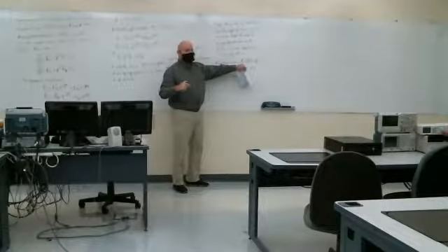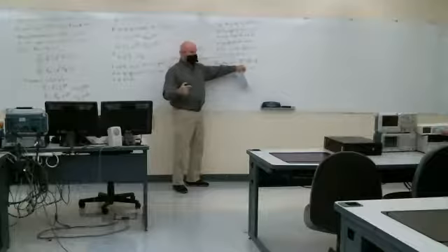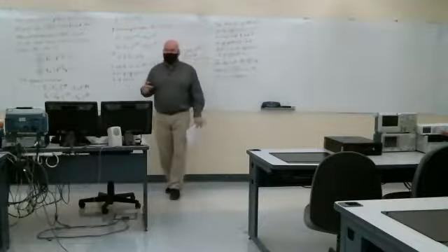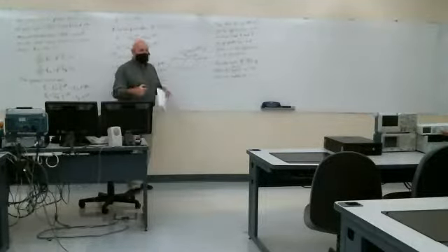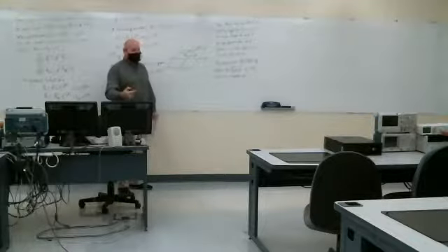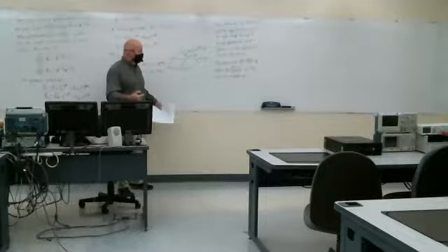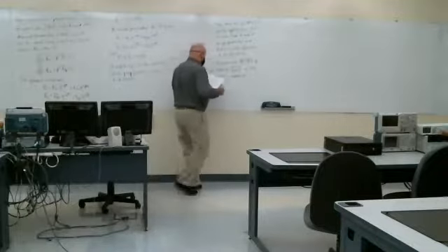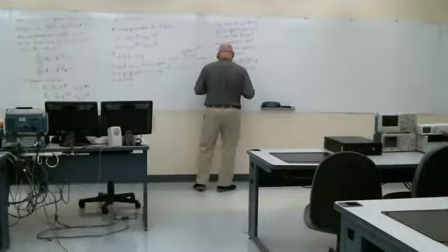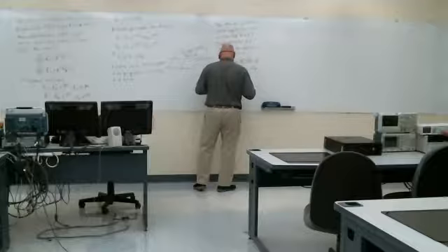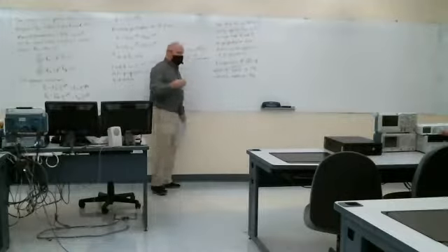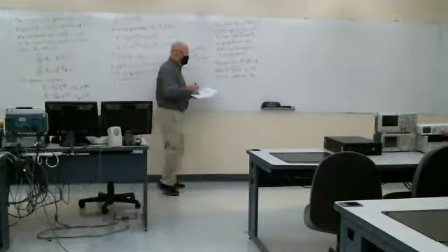Remember, E is actually volts per meter. One can express the units for E in a couple different ways, but one way is in volts per meter, and H is in amps per meter. So the ratio, the meters will cancel out, you're left with volts per amp, which is ohms. So that is an impedance. The other thing, we're working in general material at this point, so not necessarily free space.